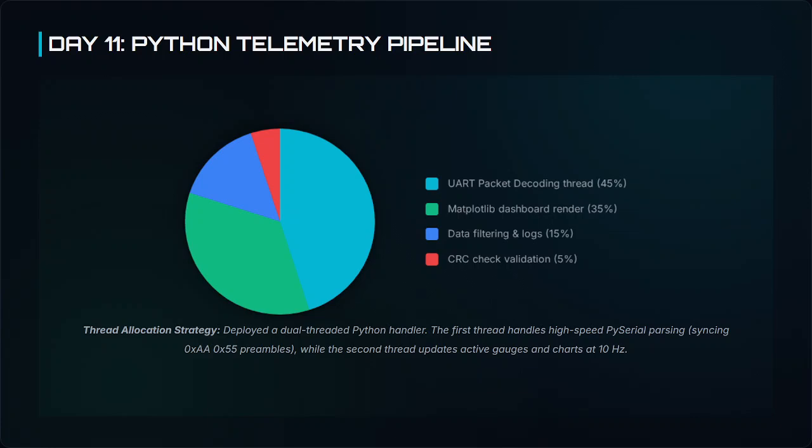On this day, we also worked on UART to connect the Proteus simulator to the Python dashboard with the use of the VSPE tool, in which we use COM1 and COM4 for communication between the Bluepill, which is a microcontroller used in the simulator, and the dashboard in Python.